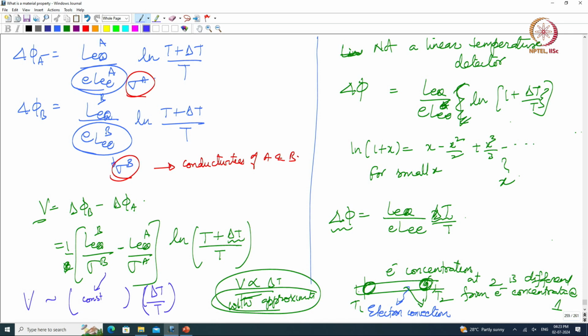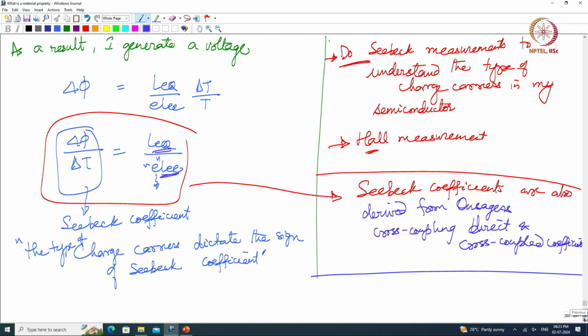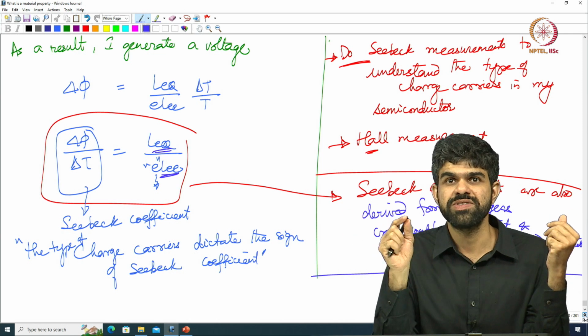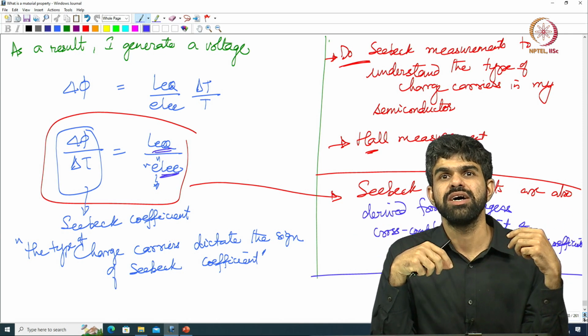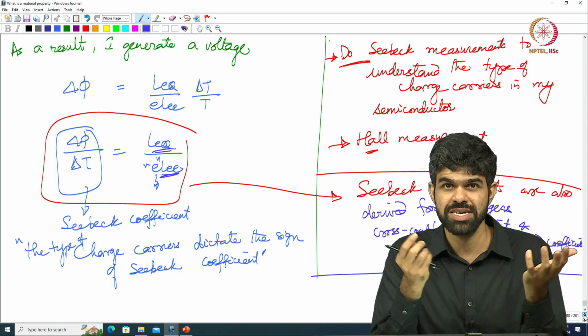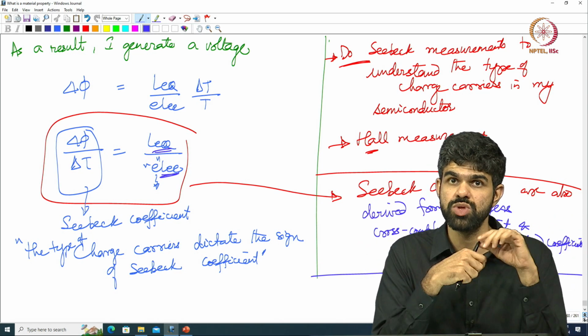Okay. So, the voltage that you generate is proportional to delta T. As long as delta T is small, you can use a thermocouple. In fact, you will be surprised, you can use it even for a 300 degrees Celsius rise in temperature. So one can use a thermocouple quite efficiently. The calibration is not that off. So even if I am measuring a 300 degrees Celsius temperature rise in my material or in a furnace, I typically use a thermocouple to do that measurement.